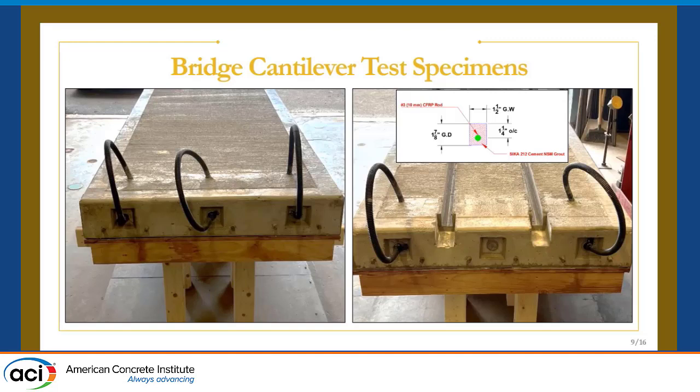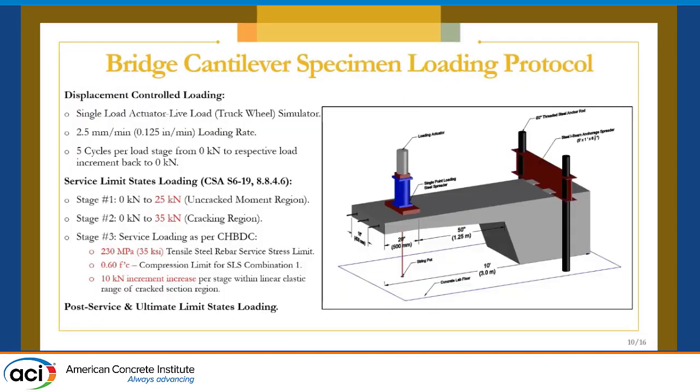And in terms of the dimension of the grooves, there would be 1.5 inches for your width, so pretty nominal for your 2x4. And then the depth is pretty much controlled by the reinforcement that's there. For us, it was 1 7/8 inches for the groove depth, with the on-center depth being 1.25 inches to your CFRP bar. So we tested the system where we post-tensioned for the control, and we applied the system for our CFRP specimen.